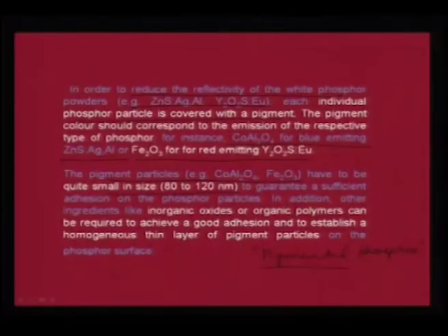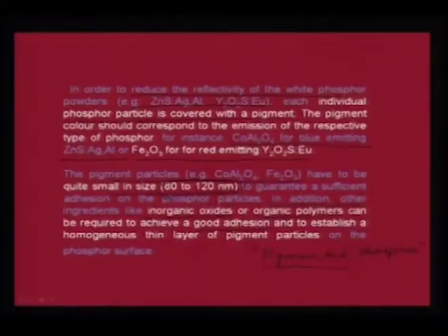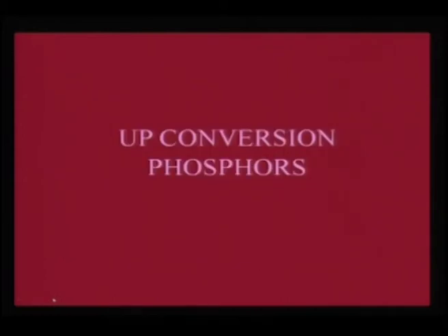As a result, the narrow range that is preferred for pigment particles is of the order of 80 to 120 nanometer. In addition to other ingredients like inorganic oxides, you also have organic polymers with good adhesion, which can coat these phosphors for getting more contrast.